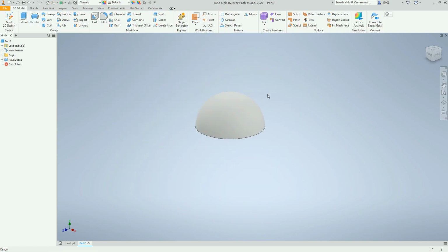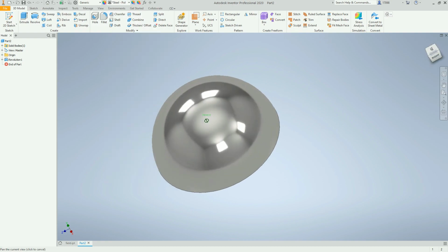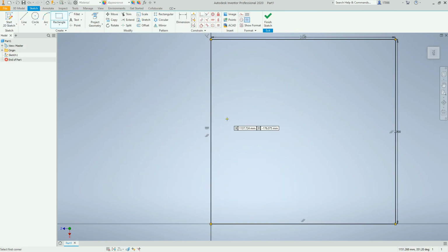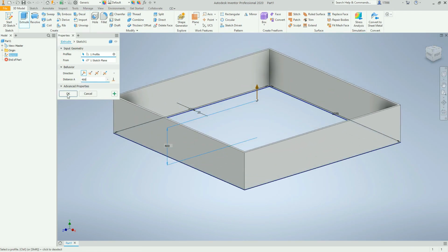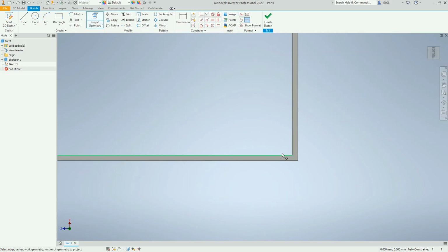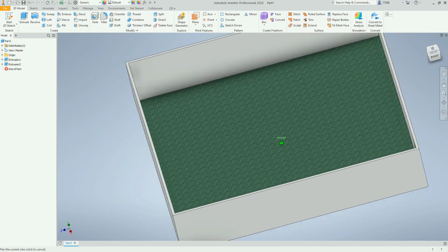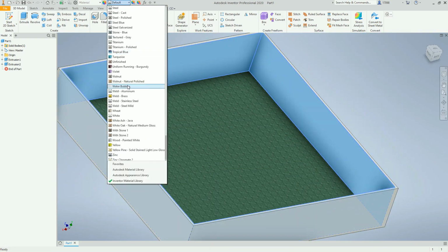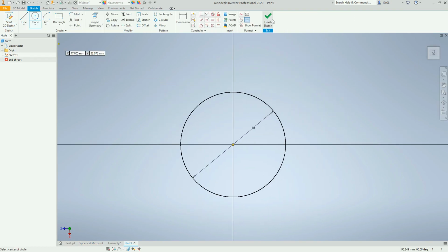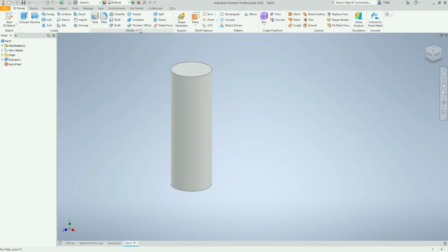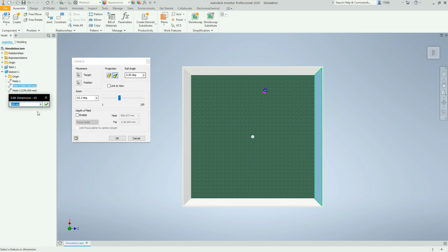The system will be modeled using Autodesk Inventor, as this software can be used to simulate a controlled environment and allows for precise camera options such as setting the focal length and field of view. The field will be a 2000 by 2000 mm area with a 400 mm high white wall surrounding it. The floor will be comprised of a green felt, and the beacon that will be detected is 50 mm in diameter and 150 mm tall. Further, it is colored bright pink such that it minimizes the detection difficulty on the software side.